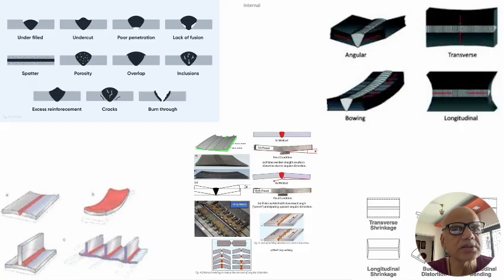And the remedial action is probably something we know: either we break the setup and try to correct it, but if that is not possible, then if we have anticipated earlier, we can give some taper to minimize the mismatch, or we try to do some wedging and excessive fixturing so that whatever mismatch or other setup defects exist, they will not aggravate further, as there will be welding shrinkage or welding distortions.